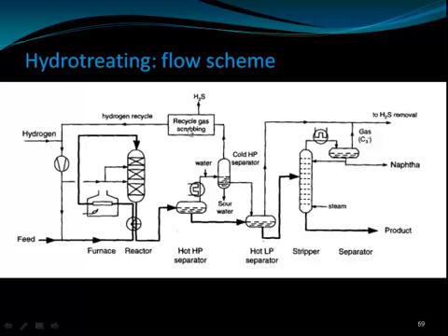The recycled gas is sent for scrubbing, H2 is sent out after treatment, and the hydrogen which is untreated is sent back over here. In the reactor, the reaction takes place with the hydrogen, so sulfur plus hydrogen will give hydrogen sulfide. Here the sulfide-removed gas will come.